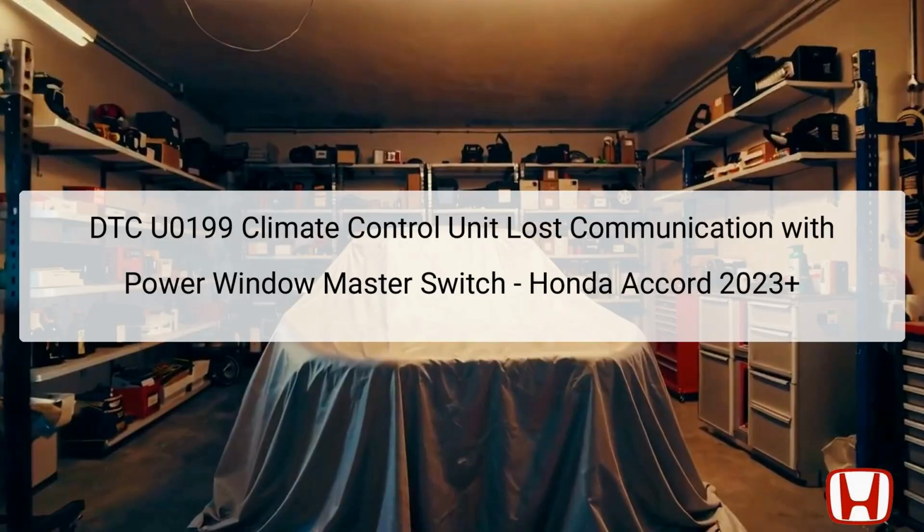In this presentation, we will be addressing DTC U0199, specifically related to the 2023 Honda Accord. This diagnostic trouble code, DTC, indicates a communication failure between the climate control unit and the power window master switch. Such failures can arise from either a disruption in the power or ground circuits of the master switch, or due to a failure in the communication network itself.